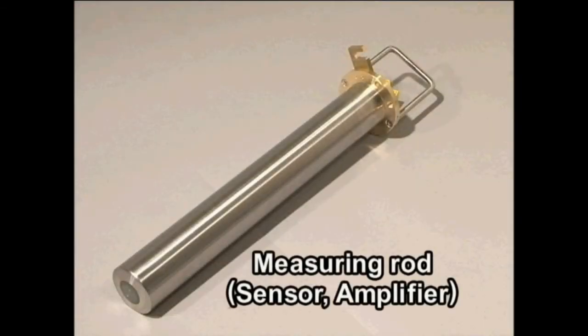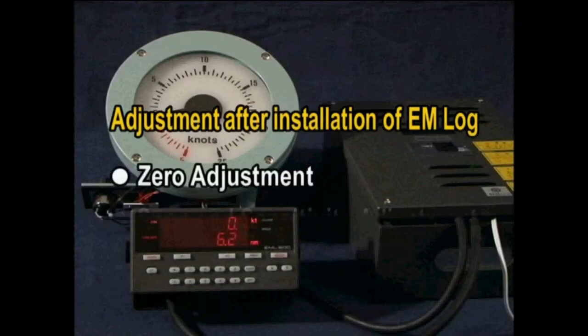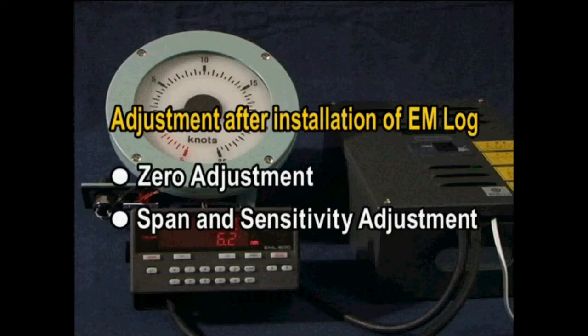Performance of the EM log measuring rod is determined by a ship's hull bottom shape and the rod's installation position. As such, the measuring rod should be adjusted to match the unique characteristics of each ship. Main adjustment items for the EM log are 0-point adjustment, span adjustment, and sensitivity adjustment.